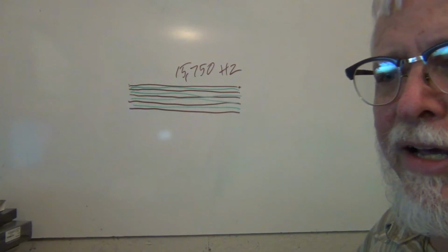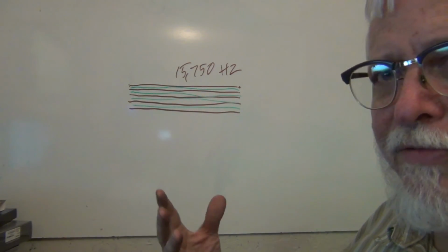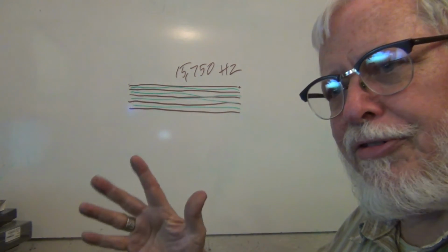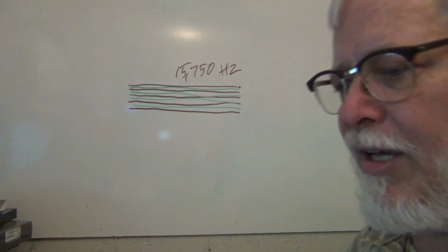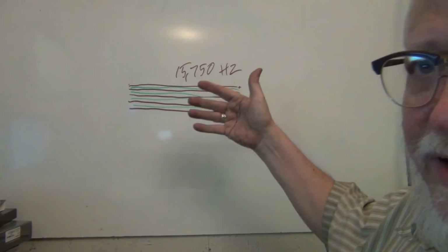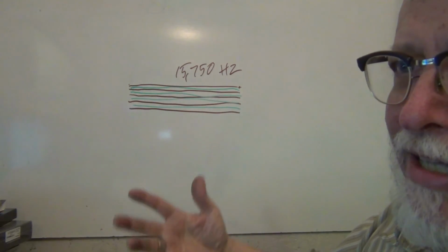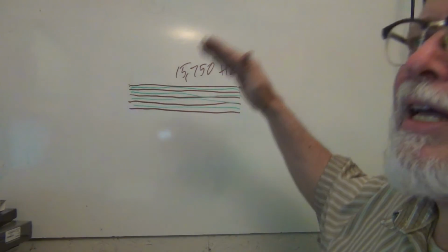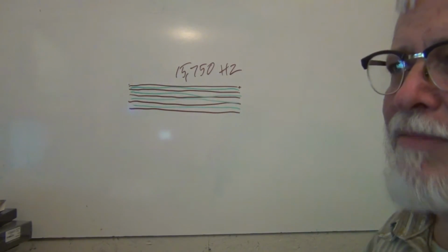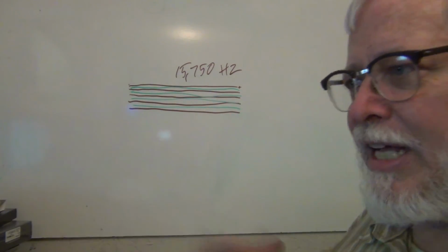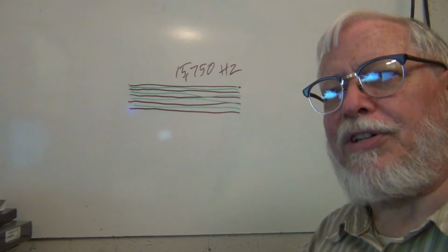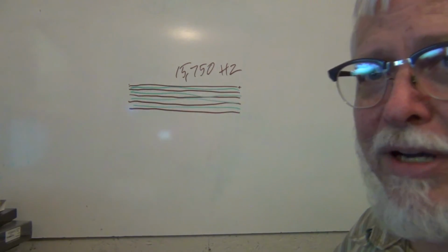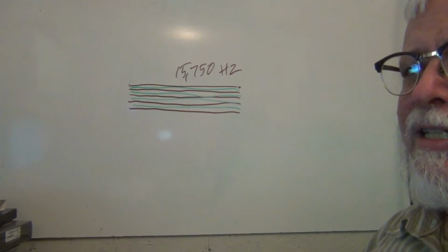And so it will refresh the picture on the screen 60 times a second, but with only half as much information. And that's why if you look at a frozen frame of video, sometimes you'll see what looks like two different pictures with slightly different timing. And that's where the two fields are frozen. They're not really meant to be shown that way, because always one comes after the other, and then another one comes after that, and another one comes after that. And your eye blends all that together, so it's like you've got a 60 frame per second video. Only you're only using half as much of the bandwidth that it takes to send that.